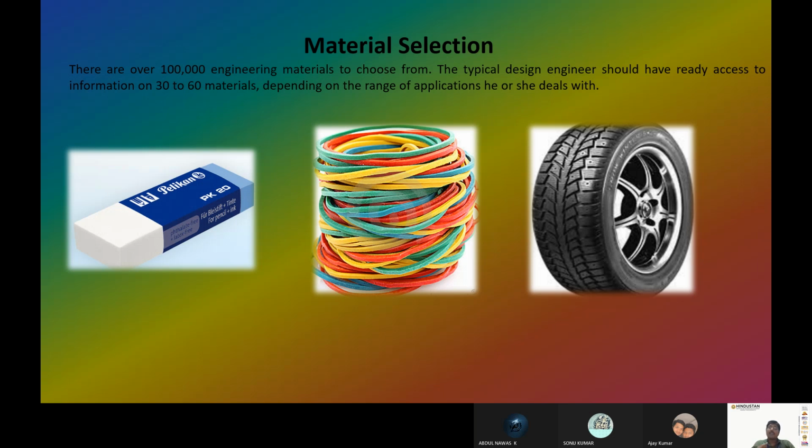And now the tire will go over it. So whether the rubber used in the particular tire is able to take care of this 70 or 80 degrees Celsius on the road, all those things should be taken care of while designing. Just imagine, sometimes these rubbers, at 70 or 80 degrees, will try to expand.